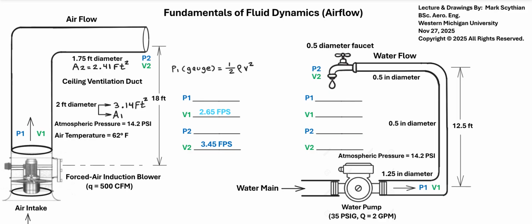If we add this to the atmospheric pressure, then we calculate the absolute pressure. So we can take a piece of the Bernoulli equation, which solves for dynamic pressure, 1/2 rho v squared. So the rho symbol here is the Greek letter rho for the fluid density, and fluids include gases and liquids. So in this case, the rho represents the air density in slugs per cubic foot units.